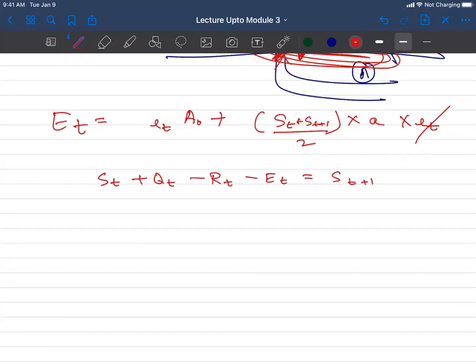There would be one more loss, by the way, which we have altogether ignored. That would be groundwater loss. The dam is not built on concrete, below it is soil, right? And if you put water on top of soil, water will try to find its way to flow through that. But yeah, we are ignoring that, and let's be very clear with that assumption, because that would add another level of complexity, and it has been shown that whenever dams are built, after a time the soil reaches saturation and the losses become negligible.